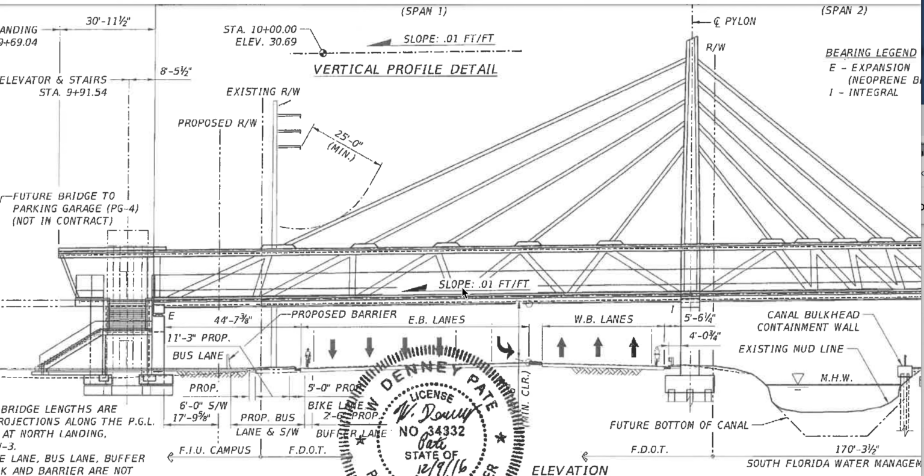So what we have here again, let's go back to this, is the deck. Imagine it as just concrete, but they added the steel. The post-tensioning is able to make it so tight. You compress the steel in here, that you're actually elongating the steel, so tense. Pull a rubber band. Hold the rubber band in each one of your hands. It's very loose as you push in the middle. Now, if you pull the rubber band tighter and put that same weight on there, it's not going to be able to push down, is it? And you pull it even tighter and tighter, you're going to be able to add more and more weight to it. Well, that's the way these steel cables work, if you will.